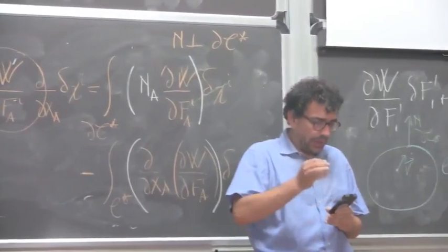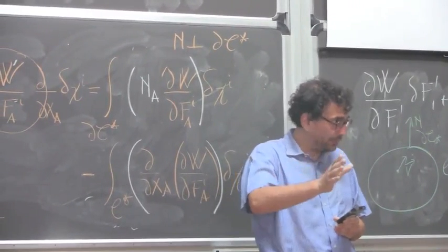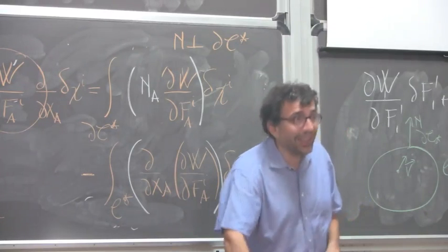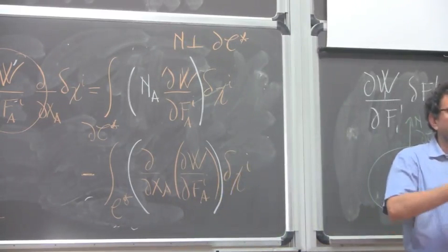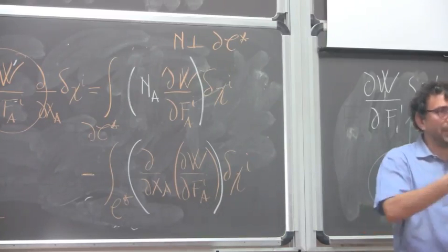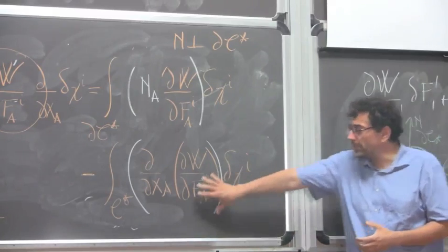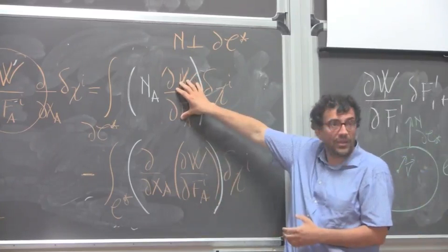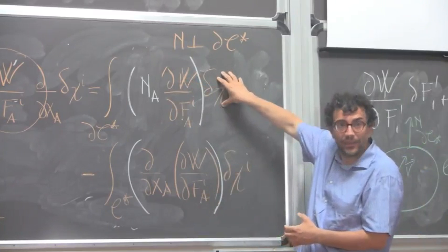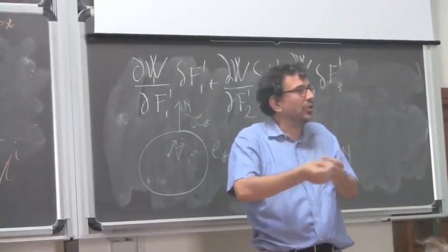So, if you have a deformation energy which depends on F, you integrate by parts. And after integration by parts, you get that the first variation of deformation energy is equal to the integral on the volume of something times delta Ki, plus the integral on the surface of something times delta Ki. For the moment, for you, this is a simple calculation, but I want to show you slowly which are the physical consequences of this.